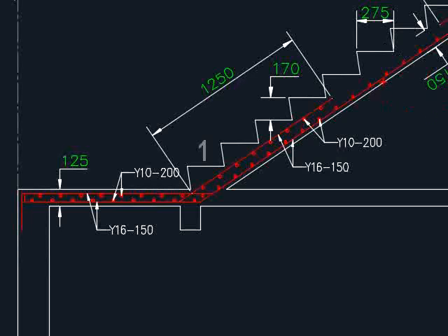Be careful with the main reinforcement bar and the secondary reinforcement bar. For the most efficient resistance to the moment, the main reinforcement bar should be placed at the position with the largest effective depth possible. This makes this the secondary reinforcement bar, which can be the nominal reinforcement bar, meant for controlling the cracks, as well as positioning of the longitudinal reinforcement bar.